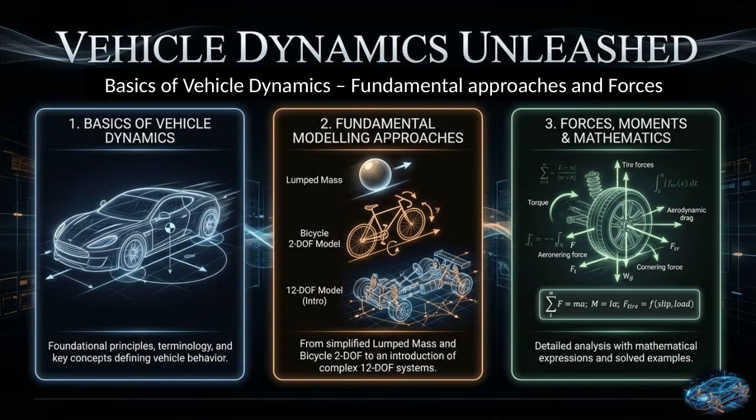Today's session will cover three major areas. First, the basics of vehicle dynamics. Second, the fundamental modeling approaches, including the lumped mass model, the bicycle model, and an introduction to the 12 degree of freedom model. Finally, we will discuss the forces and moments acting on a vehicle with mathematical expressions and solved examples.